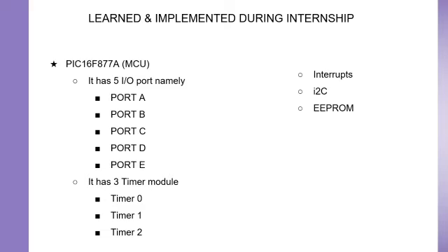Interrupt. An interrupt can originate from both MCU internal and MCU external devices. An interrupt from an external switch or sensor, for example, is sometimes called an attached interrupt, as it is generated by an external device attached to an IRQ interrupt request pin on the microcontroller unit. When the relevant state change occurs, the external device sends an interrupt request signal to this pin, and this in turn generates a notification to the MCU's interrupt control.